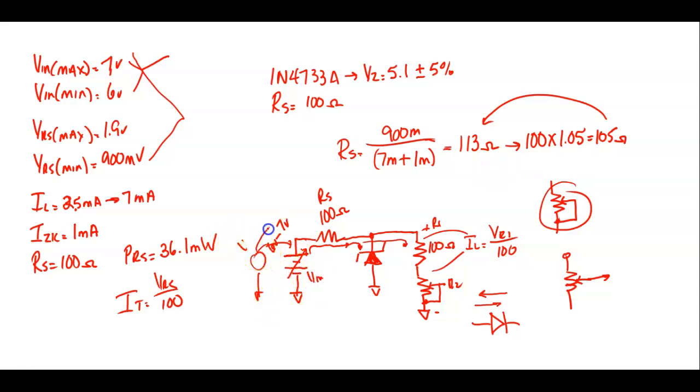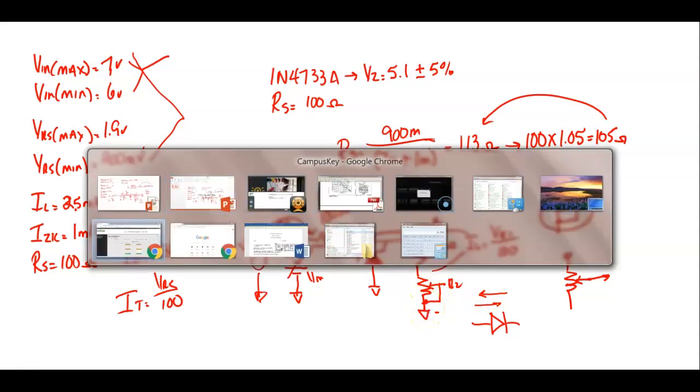Okay. So I have my meter lead. I have it on this side of this resistor, and then I have it on circuit common. Okay. Right. And I'm setting this to 6 volts. Y'all understand? Everybody okay? Yeah. So to set my input voltage, what I'm going to do is change my power supply. Okay. So this is common down here, so y'all can see the placement of my meter leads.